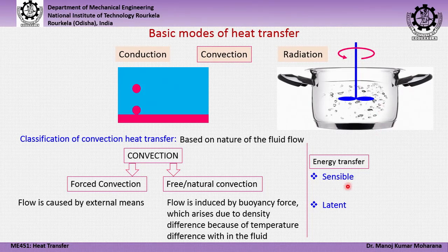So, the energy transfer that will happen in this situation as described here in this problem will be by means of two ways. One is called sensible energy transfer and second one is called latent energy transfer. The sensible energy transfer indicates the transfer of energy from the solid to the ambient fluid because of single phase heat addition, or it may be a reverse process, single phase heat subtraction if we are cooling the liquid.